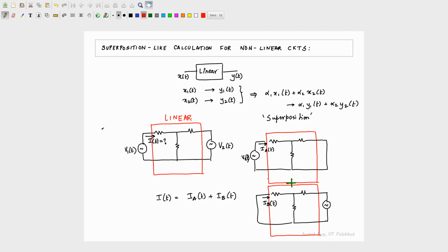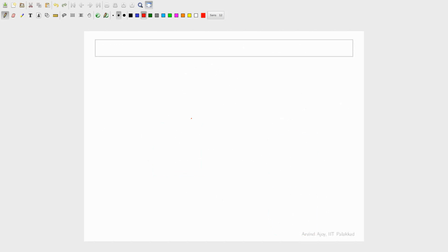not at different times, not different omegas also, but what we have, I think, got an idea for intuitively, and I mentioned it sometimes, that if you have a nonlinear circuit, you first solve for the operating point in some way. You either use a computer to solve, or you make some crude approximations like we did for the diode. You make some straight line approximations and you try and find out what the operating point is. About that operating point, you do a small signal incremental analysis.